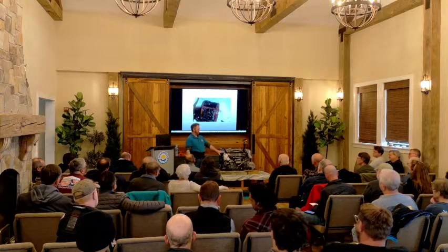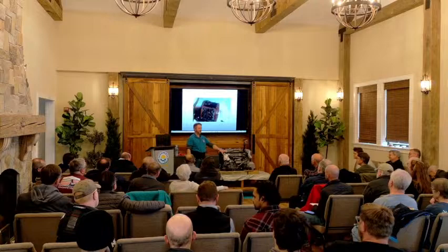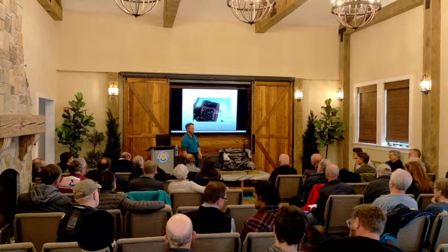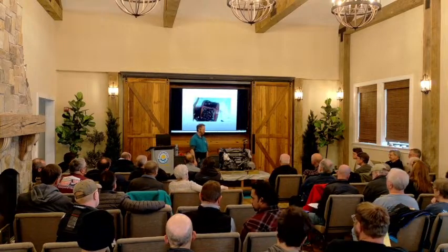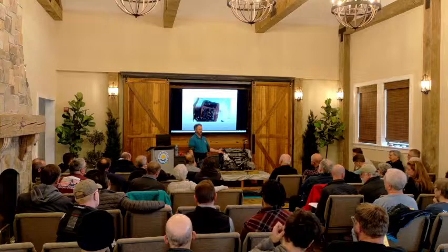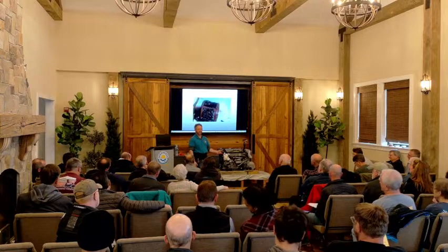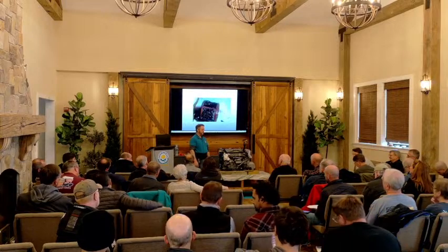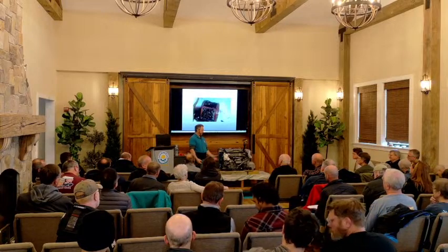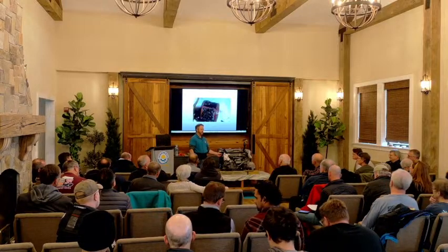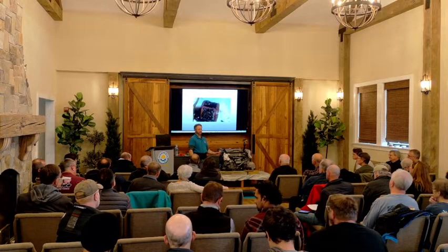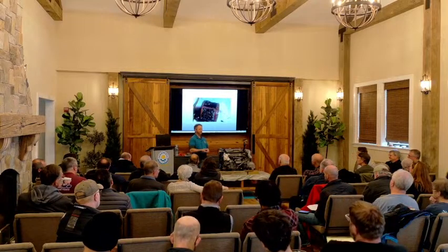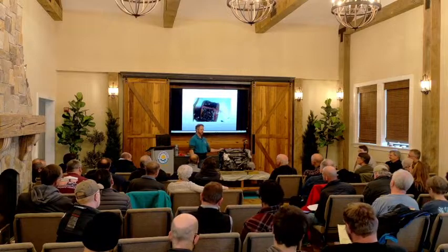And so you can upgrade to, like, this white one is a Balmar, which is the most common upgrade for people, the brand that they use. And even Yanmar offers it as an upgrade when you go to buy the engine. It's up to you. Just got to remember our engines are metric, so make sure you're buying metric stuff. So if you go to NAPA, they may give you a metric belt or not. It's hard to say.